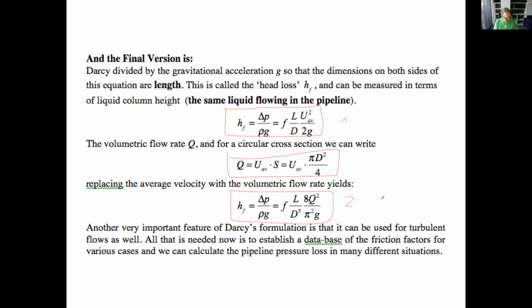What is the significance of that? It's very elegant. Okay, so you're not getting excited. Let me see. We have a water tunnel in the city, in your neighborhood, and then there is a pipe here, and somehow you open it up and you have a jet. Then delta P is basically rho g H. If there is no friction, then the velocity is the square root of 2gH.